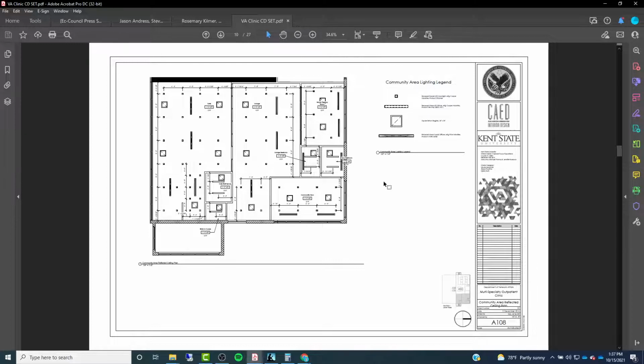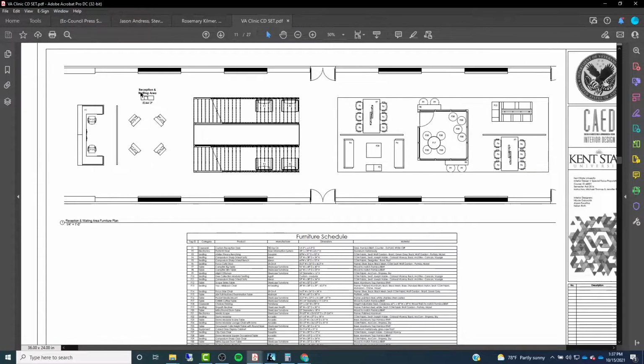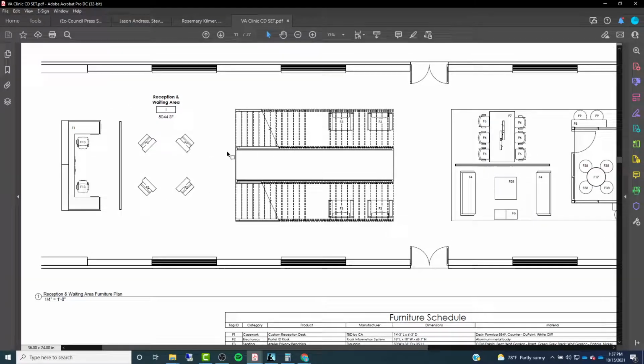Again, more ceiling plans, so more lighting legends. And then we have furniture plans. If we look at these furniture plans, these are basically just giving us the furniture layout. So there's not going to be any dimensions on this plan unless they're critical and necessary for the placement of something, right? Usually though, you're not going to have to worry about dimensioning anything on a furniture plan because the placement of furniture, it's all movable, right? You don't have to really worry too much about being precise with it. As long as they place it in the general area, in that layout, it's usually fine.